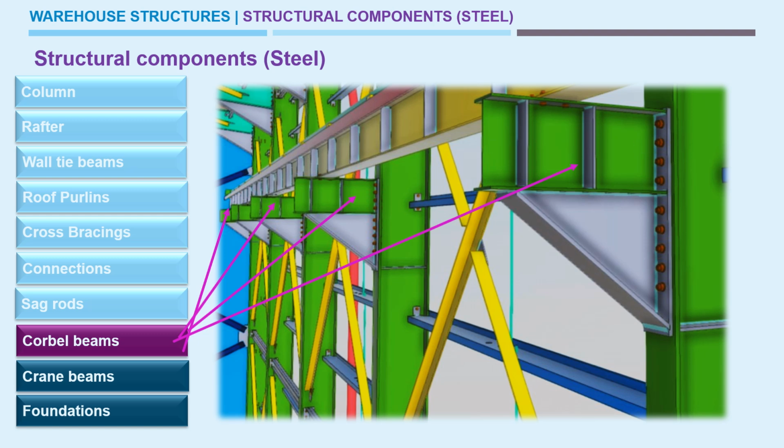So this requires haunches to hold these bolts. Also, stiffeners between the flanges and the web are provided. So this is to hold the heavy crane capacity.